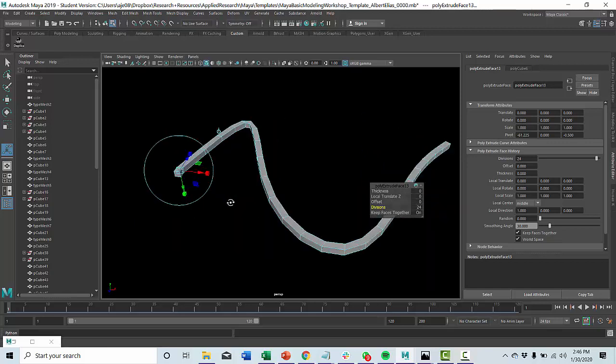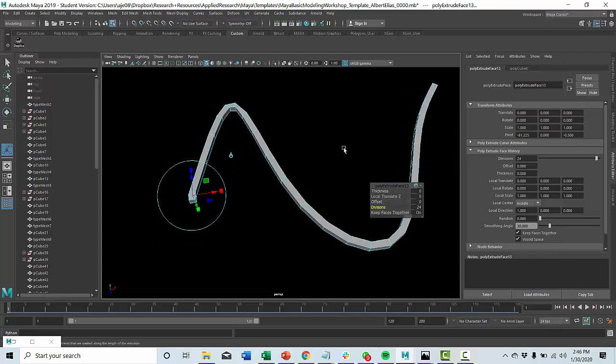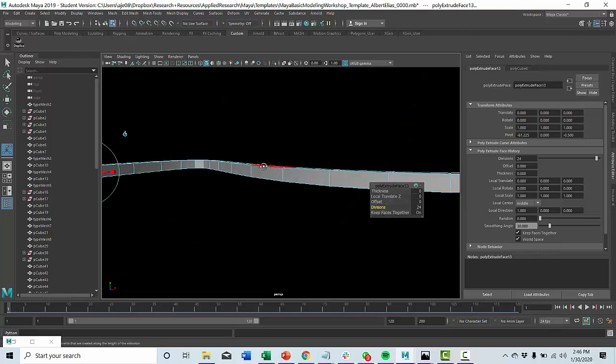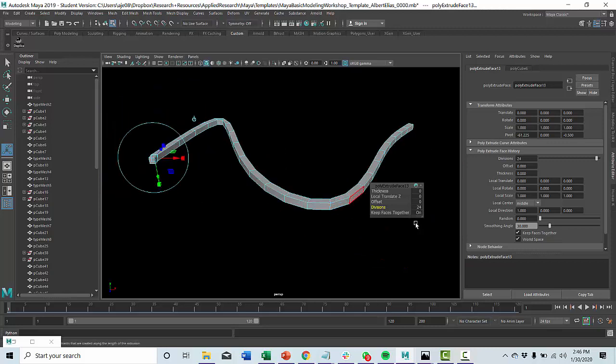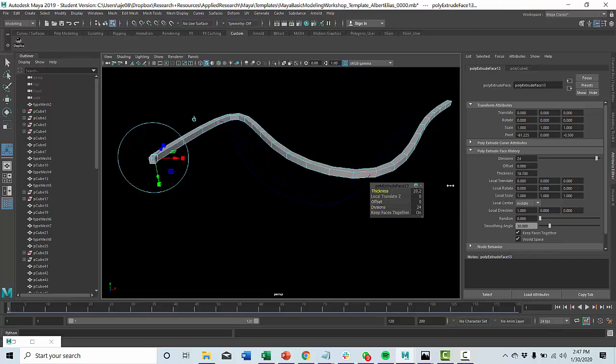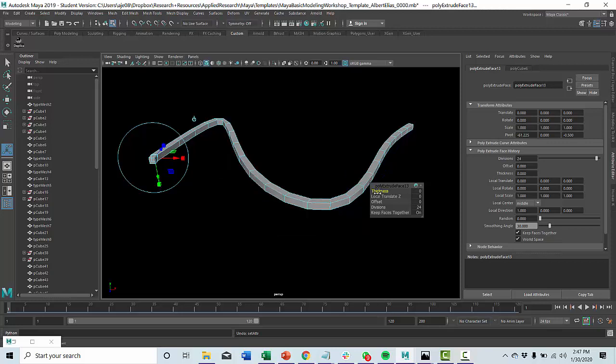So very quickly, if you have curves that you've drawn out or sketched in Rhino or another program, you can start to extrude along those curves and start to get more complex geometry, kind of like a sweep, right? In this case, you can also change the thickness, which I guess just makes it extrude further. I mean, these don't really help you too much. I guess the only one that would be helpful is if you were to offset it, right? So it could taper if you wanted to.